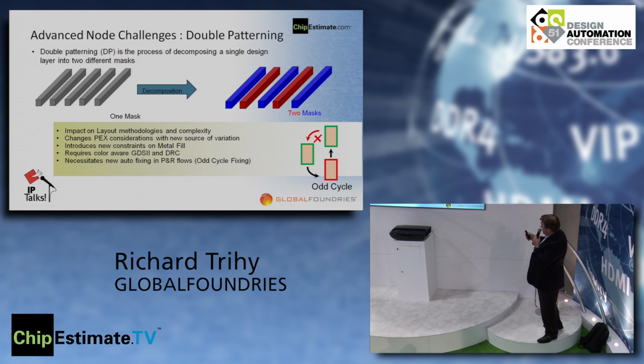The odd cycle is shown here on the right. The definition of an odd cycle in GlobalFoundries terms is that if you have an odd number of shapes, there's no way to achieve a decomposition that meets the rules. And you can sort of see it here. I have two greens in close proximity. I have two choices to fix this. I either have an even number of shapes where I have a red in between these two, or else I have to space them a little further apart. Okay. And this is what auto-fixing is about in the place and route flows.